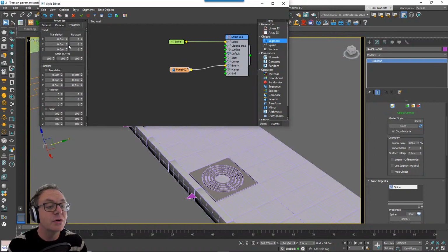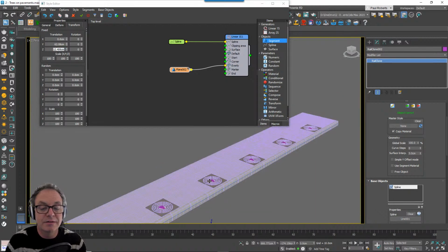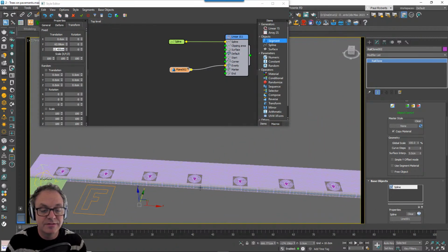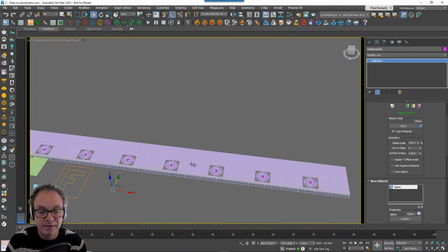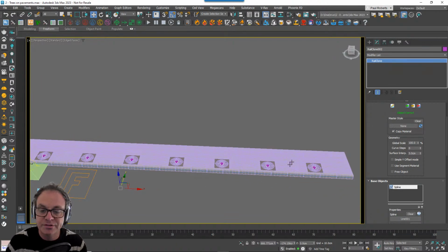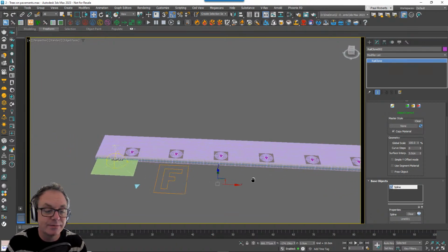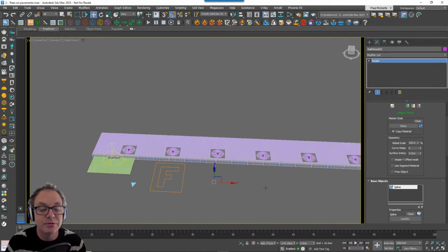So I'm going to go to transform, and I'm just going to do that manually. So I'll just increase it on the Z axis a little bit, move it back on the Y, and maybe down a little bit there. Okay, and that's our RailClone object done for the trees. And what will happen obviously is if I change this spline, then the markers will update to match perfectly the basins. Of course, if I change the distance between the basins, I'll need to do the same for this object too. And then once you've done that, you just pop into Forest Pack.